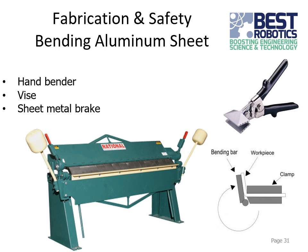Sometimes you may want to bend pieces of aluminum. So they have these special bending tools. You can use the sheet metal brake, the big thing shown here. That gives you a nice edge to bend along, and it can help you with the bend. They have hand bending pieces, but just a vise can work really well for that.